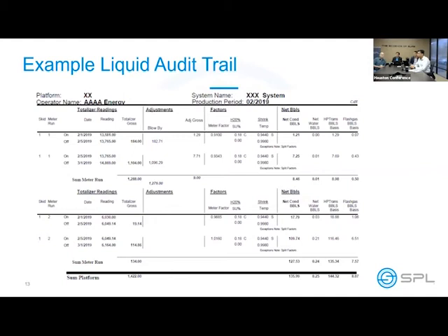So we simply would totalize our gross readings, multiplied times a meter factor, multiplied times the water percentage, and multiplied times the shrink factor and times the CTL in order to calculate the actual net barrels.